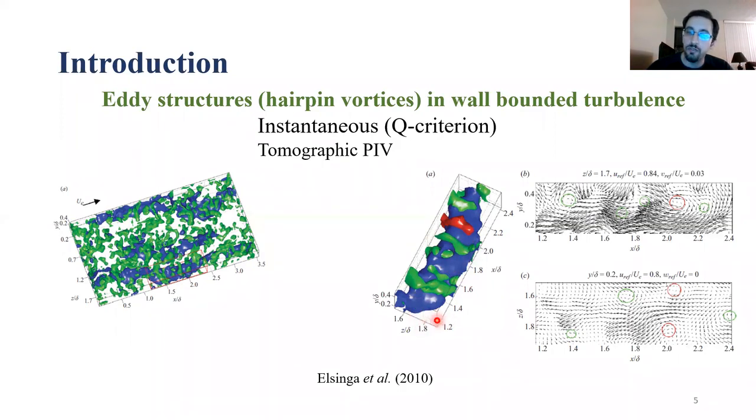And if we look at the cross sections, for example this wall-normal streamwise cross section of this flow field, and look at the velocity vectors, you can see where we cut through the eddy structures. We have these swirling flow regions around the eddy structures. Also on a spanwise, streamwise cross-stream plane, again we see these rotational flow fields when we cut through the eddy structures.